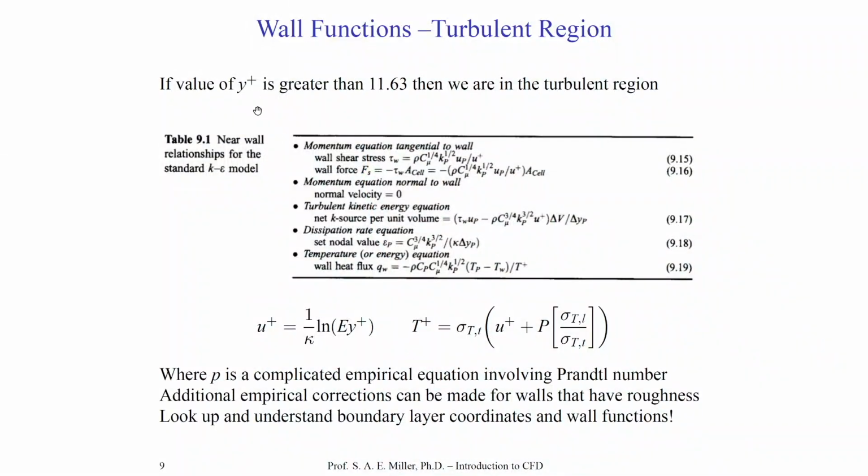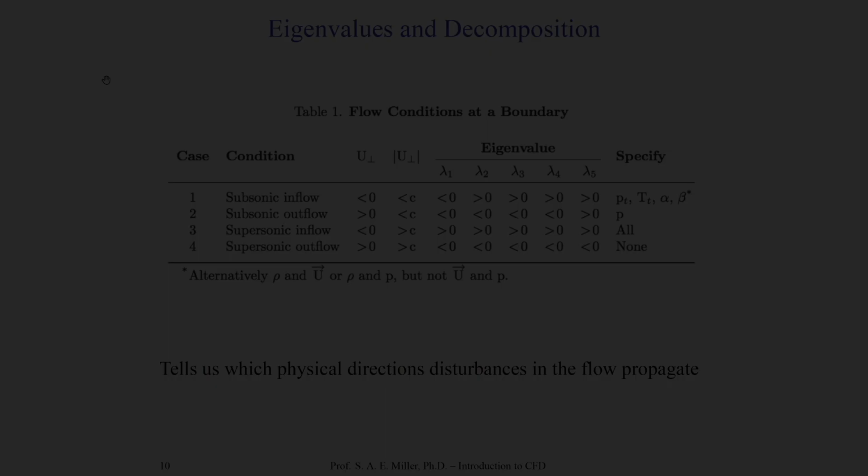And typically, you would set the y plus distance in your boundary layer to be approximately 1 or 2. Now the first grid point is on an order of a factor of 10. So you're getting a factor of 10 coarsening of your grid in the boundary layer on just a rough estimate for these types of cases.